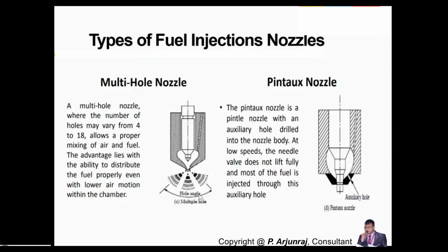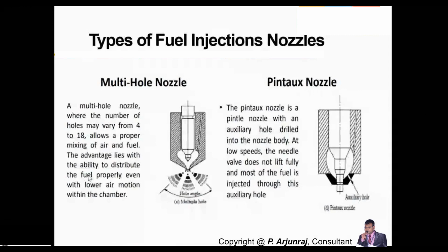What should be the injection quantity? What should be the duration of the injection? Even that can be avoided. Okay, the advantage we have in the case of multi-hole lies with the ability to distribute the fuel evenly and properly with low air motion within the combustion chamber.